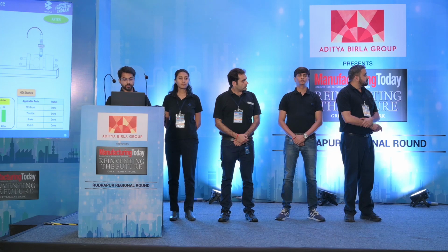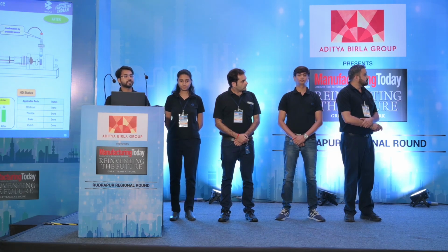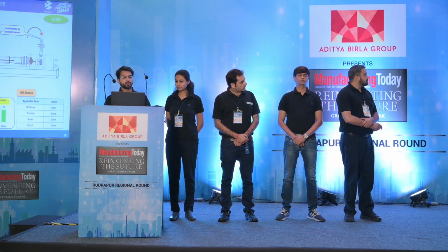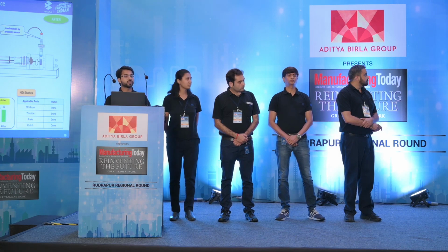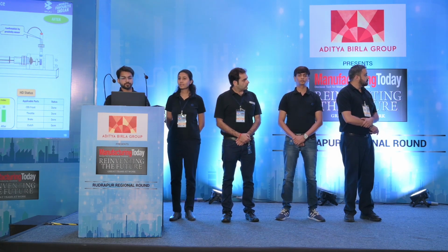First, we have provided a proximity sensor to ensure correct resting of the die casting end in its defined reference slot. Secondly, we have provided a touch sensor to ensure that the inner reaches up to the cutting plane. Both these sensors are interlocked with the machine cycle.